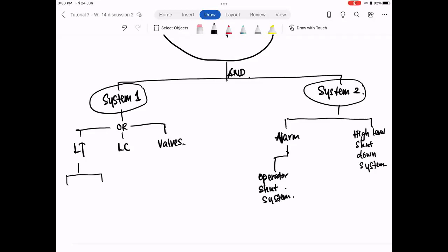But for us, we stop at what we can control, because if it has failed, we change it. Why it failed any further is under manufacturing. If you are working in valve manufacturing, then you want to break it down: this valve failed, I have 5 parts that can fail, and for each part, what are the potentials that it fails and what could go wrong. But as a user, we most likely will stop here to look at the failure rate.